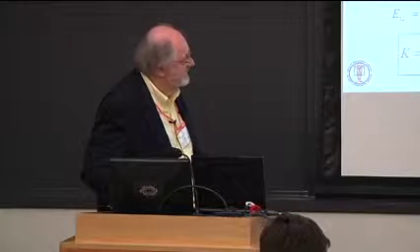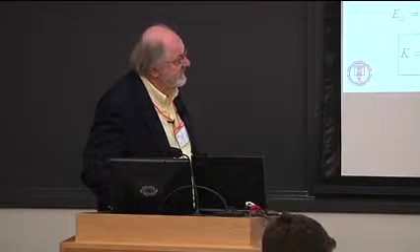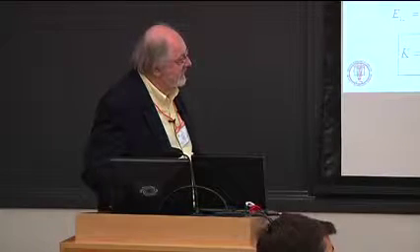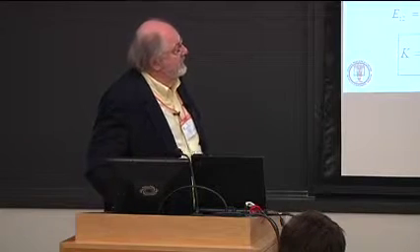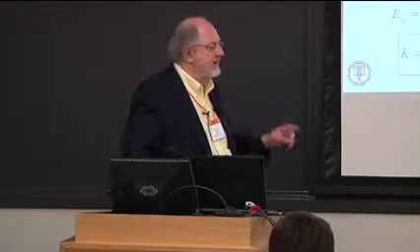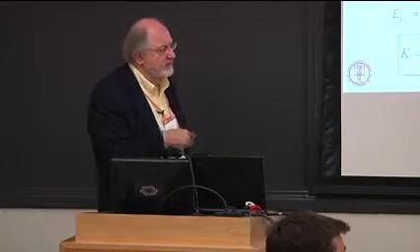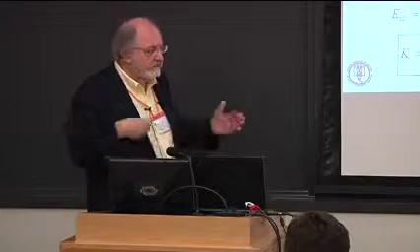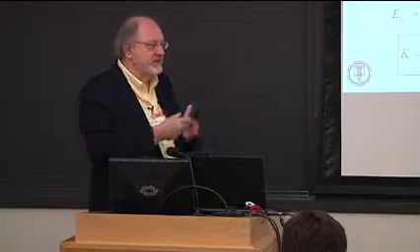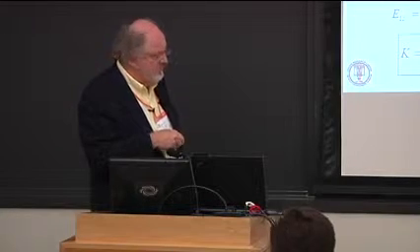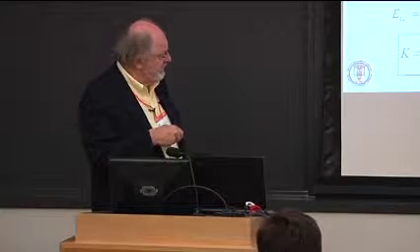Just one last question. About the application of the collision theory here, you would have to deal with the fact that there's still an interaction of molecular forces before they get into contact. You mean like a Lennard-Jones interaction? Yeah. That's kind of in this collision efficiency term here, because essentially this accounts for the flow field effects as the droplets approach each other, whether they actually are going to collide or not. But typically, because the gas viscosity is so low, this number is typically unity.